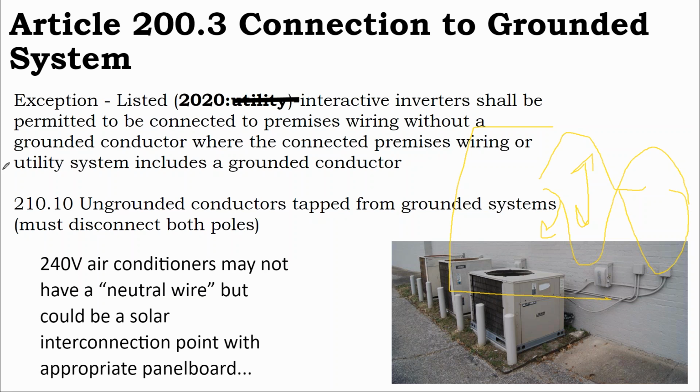And because these two phases are perfectly balanced, the air conditioner is drawing its power from both phases equally, whereas you might have on an electric service panel a different load on the right side of the panel versus the left side of the panel because they're doing different things at different times. An air conditioner is using that 240 volt circuit uniformly.